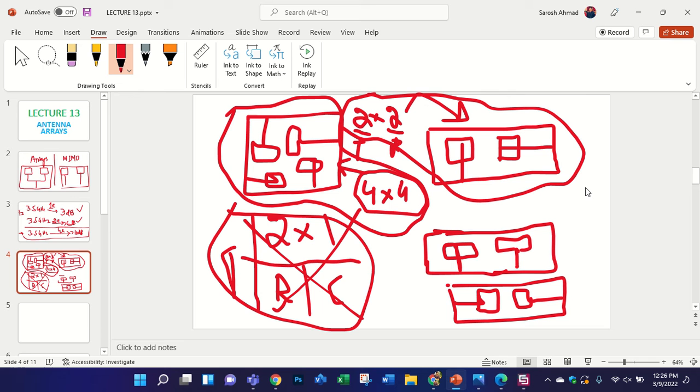Excuse me, Sir Sarosh. I want to ask how to simulate the receiver antenna in CST. How to get the result for the receiving antenna, not the transmitting one. When you simulate your MIMO antenna, you will get many results like S11, S21, S12 and S22. The first two, S11 and S22, behave like a reflecting antenna, like a receiving antenna. The other two, S12 and S21, behave like transmitting antennas. So if you have a 2 by 2 antenna, both antennas work as transmitters and both work as receivers. S12 means how much effect the other has, which is also called coupling, while S21 is also called transmission.